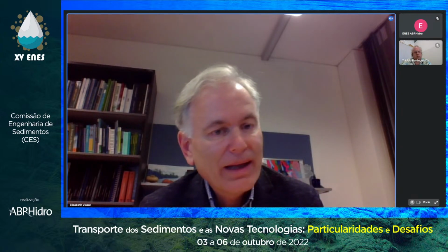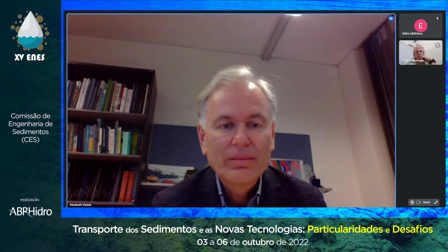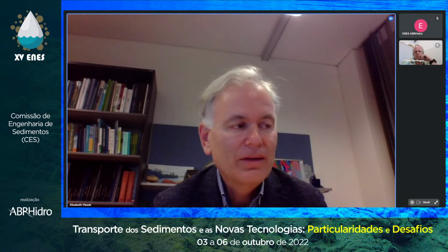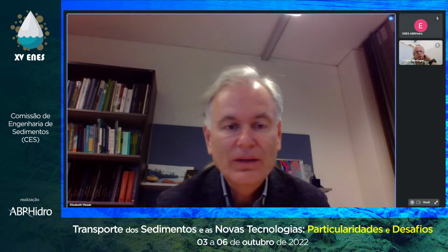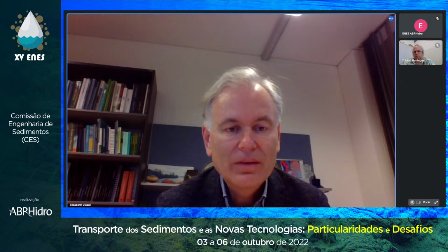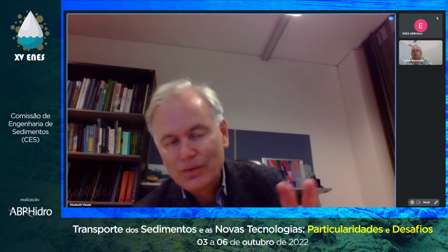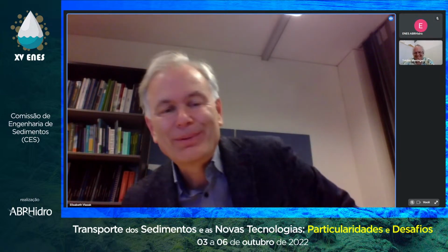For the coarse material larger than 1 millimeter, there are long-term effects like bed level changes. So it's quite clear we have to measure the cross sections downstream and see what the change is there. But we should also take grain size distributions from time to time, because then we see whether the erosion is leading to a coarsening of the riverbed, or whether it gets finer. So grain size is another parameter, additionally also the morphology and so on. I could talk too long about this, but I guess these are some parameters we could have, and of course also the environmental parameters.